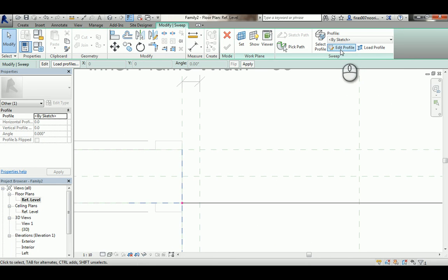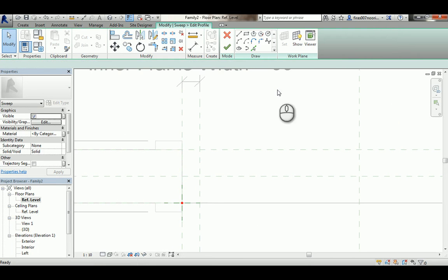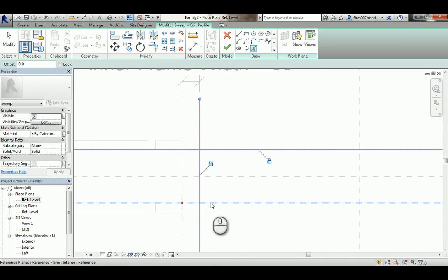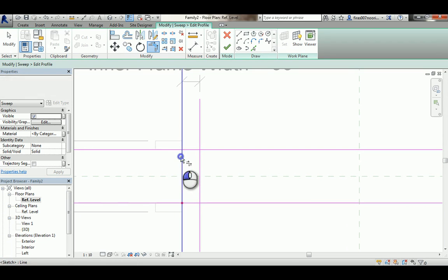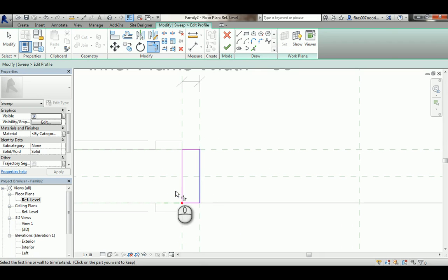and now to edit the profile itself, you need to pick lines here or pick reference, select this, lock, this, lock. Careful here not to select the face, just the reference plane, lock. Again, the reference plane and lock. I'm going to hit on my keyboard TR, which is fillet. Select both two corners to get rid of the extra lines, and you get that shape now.